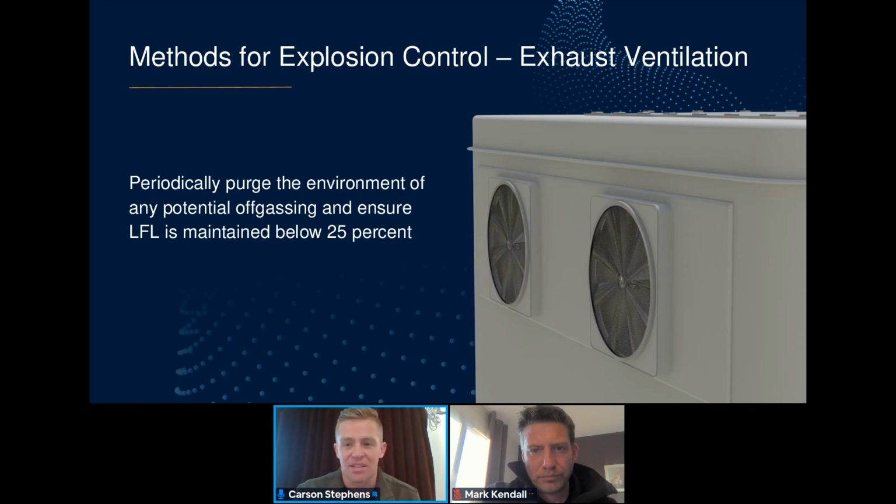The only downside to this, and we're going to talk about when to apply each layer of protection, is you can't just vent this explosive gas everywhere. If you're in the middle of the ocean, or in the middle of a desert, perhaps air permitting isn't required. It's really subjective. I can tell you that where we are at the moment, Mark's in France, but I'm in Phoenix, Arizona, you're not going to do it in Phoenix, Arizona. So it's really imperative that you monitor what your localized codes are and implement exhaust ventilation if you're allowed to. But it is an effective form of explosion control.